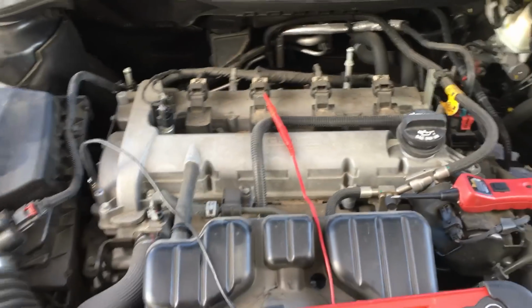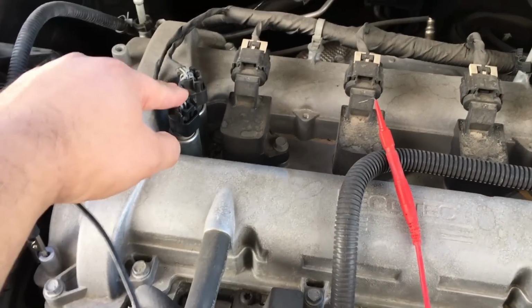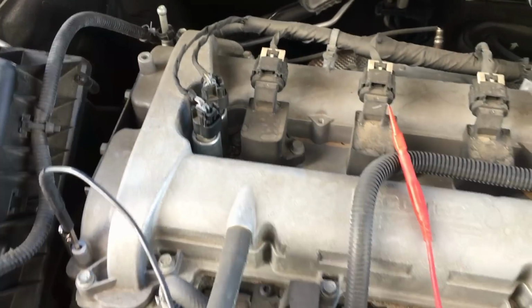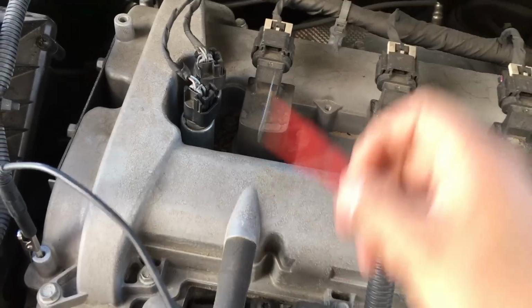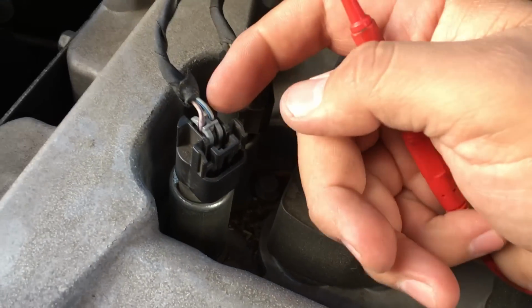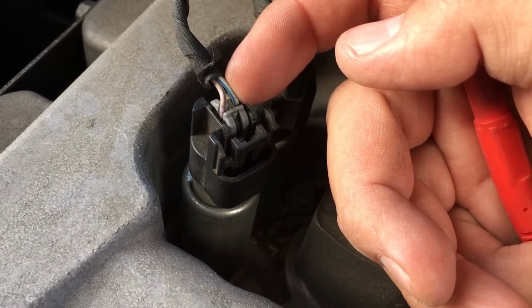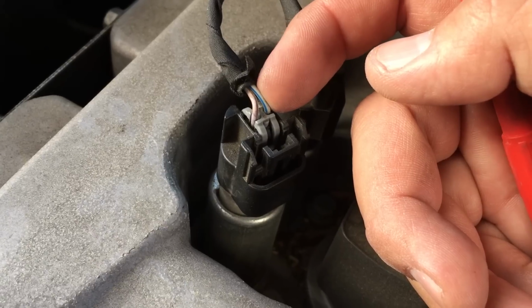Now, to be honest with you, under normal circumstances, I would have already just replaced these solenoids because I know they're a common failure item, but for the sake of the video, we're going to do some testing using my lab scope. I've already got my lead hooked up right here. Now what we're going to do is identify the two wires. Again, if you look here, we have the two wires. This is the gray and blue wire, which according to the wiring diagram is our power feed that comes from the computer.